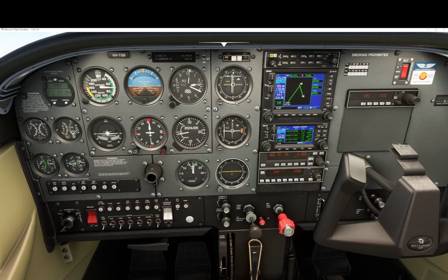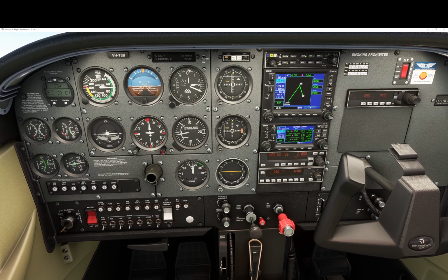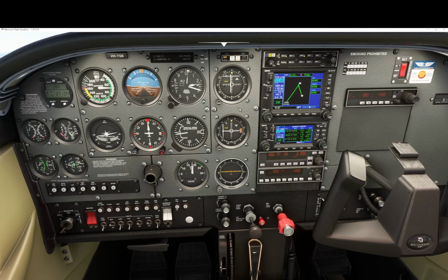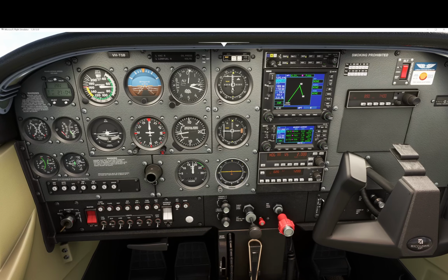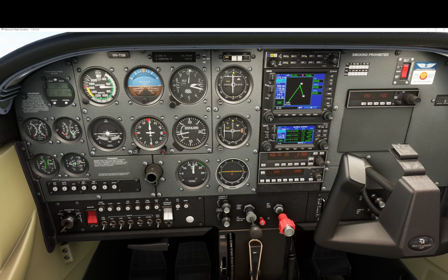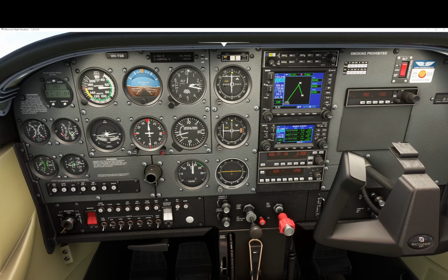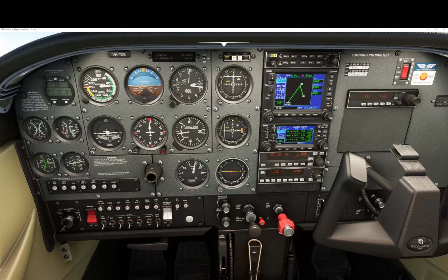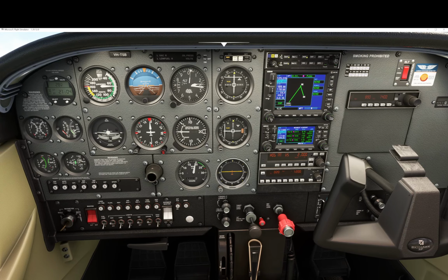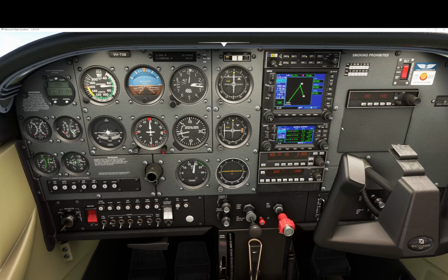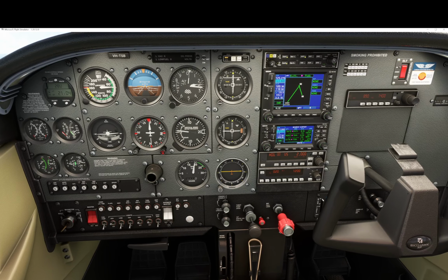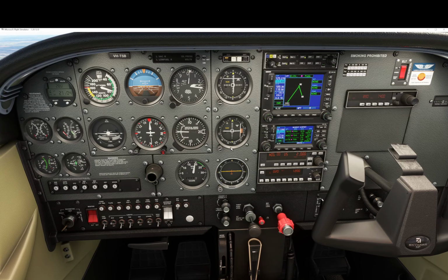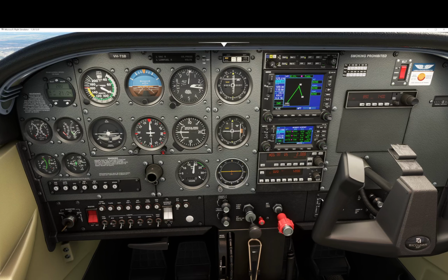So I'm on the ILS. If I swing it a little bit over to the left here, I can come online with the lateral alignment. I can bring the CDI more to the middle, and I'm too slow. I'm down to 70 knots. I want to bring my RPMs back up to about 2,000, bring it up to about 90 knots. I'm going to tune this to 071, pick up that 071 radial off of Memphis. My speed's climbing up pretty fast here.